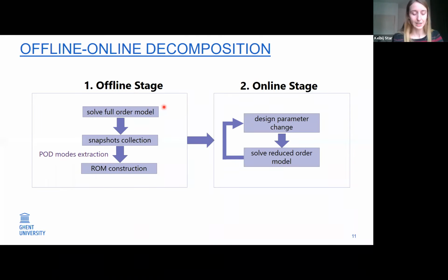Basically CFD simulations. And out of those simulations, you get what we call the snapshots. You get your flow fields or temperature fields, pressure fields, and you collect snapshots over time. Usually they're transient simulations, so you run over a certain time period and you collect snapshots in time, and then I apply POD. So really POD is applied to extract the features of my complex full order model.